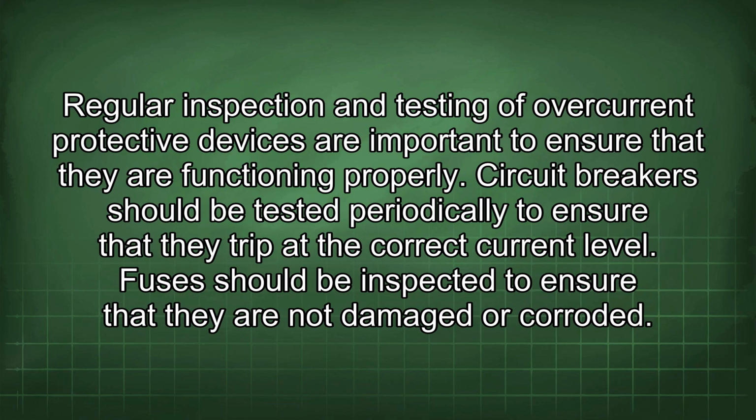Regular inspection and testing of overcurrent protective devices are important to ensure that they are functioning properly. Circuit breakers should be tested periodically to ensure that they trip at the correct current level. Fuses should be inspected to ensure that they are not damaged or corroded.